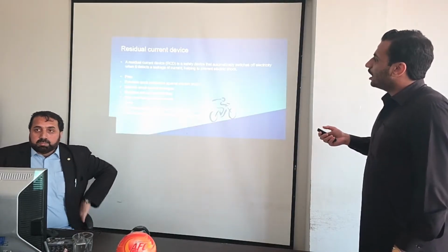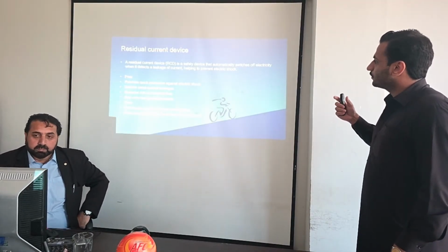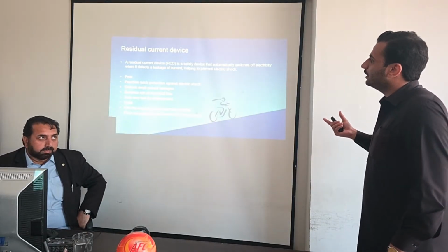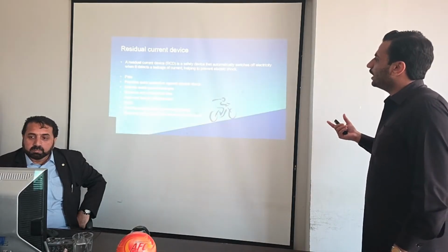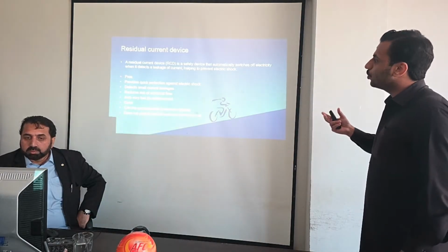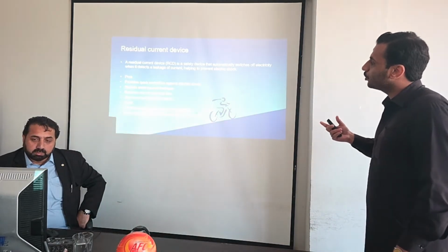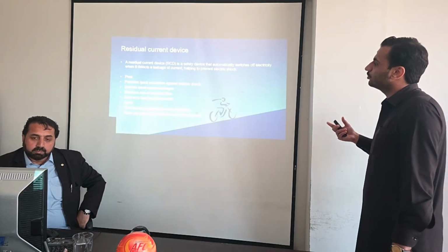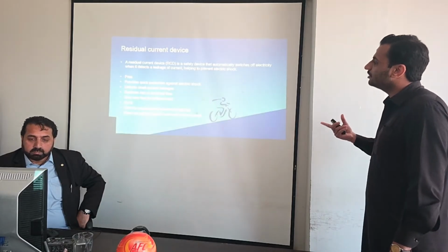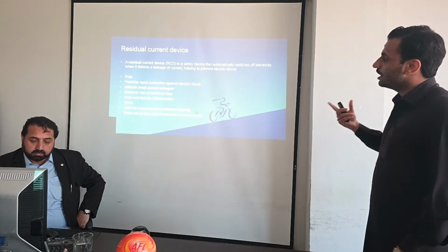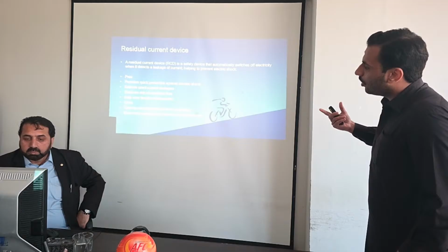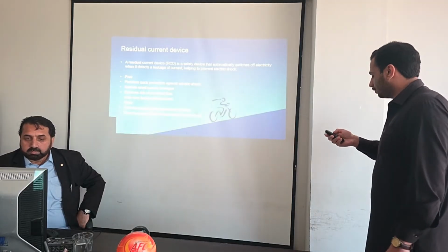Residual current device. What is RCD? It is a type of protective measure which automatically switches off electricity when it detects a leakage of current, helping to prevent electric shock. It automatically trips when it detects a leakage. So what are the pros? It provides quick protection against electric shock. It detects small current leakage, reduces risk of electrical fires, and acts very fast, in milliseconds. And what are the cons? It can trip unnecessarily or does not protect against overload or short circuits.